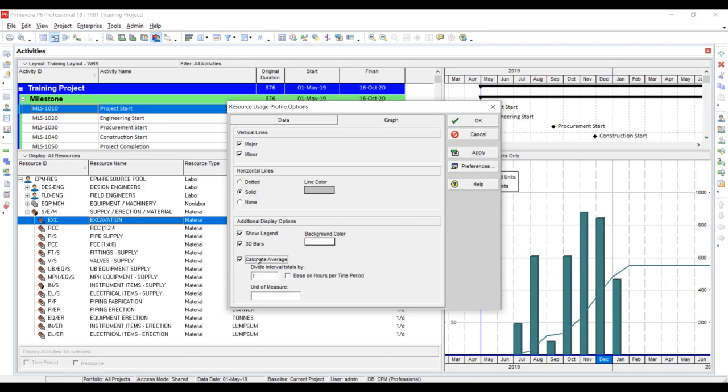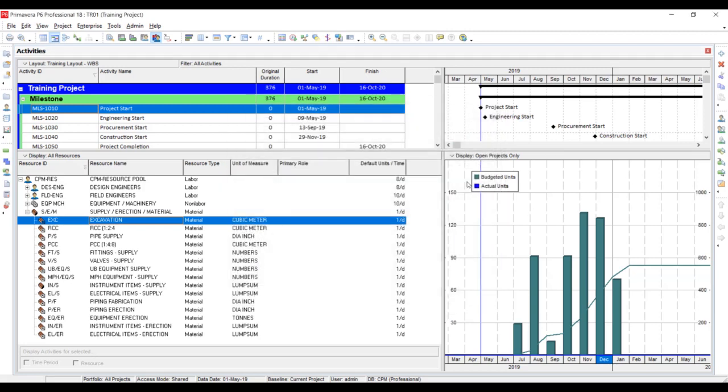And if you want to see the man hours converted into man days, you can simply divide this interval by 260, and you can see the effect of manpower. Man hours are being converted into man days. For example, one person works 26 days in a month and 10 hours per day. So it means that 26 multiplied by 10 is 260. So if I divide man hours by this, you can calculate the man days. I will click OK, apply, and you can see the vertical axis being shown here.